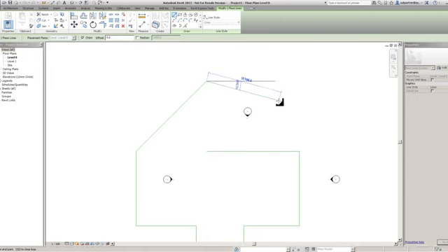What we also have, if we just look down here at the bottom of my screen, we can see it says SZ to close loop. Now, this is very similar to in AutoCAD, how we press C, enter to close any loop or chain that we're in. Works slightly different. If I just press SZ, just key punching in SZ on my keyboard, what you see is the lines come around and basically snap to the start of where I started that chain. Now all I do just to input that is left click.